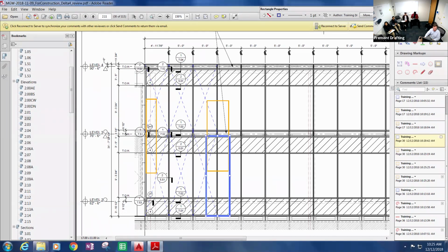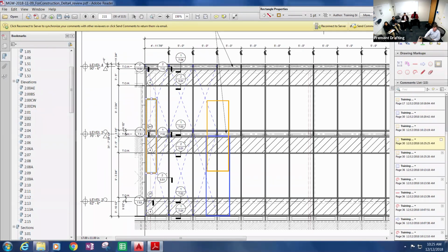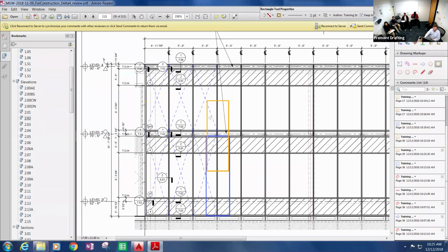And so then sometimes we run into cases where this upper unit maybe doesn't go up to a floor, but goes up to a soffit. In that case, those units are actually dead loaded onto the unit below. So I might end up having this tributary area for dead load applied to that anchor also.